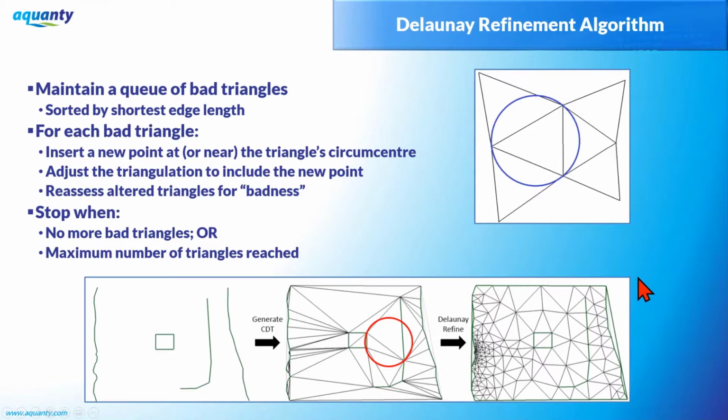A Delaunay triangulation comprises a set of triangles with the geometric property that no vertex of any triangle is contained inside the circumcircle of any triangle. When this is applied to triangular grids, this maximizes the minimum angle of any triangle in the grid, thus avoiding poor quality, narrow, high aspect ratio triangles.